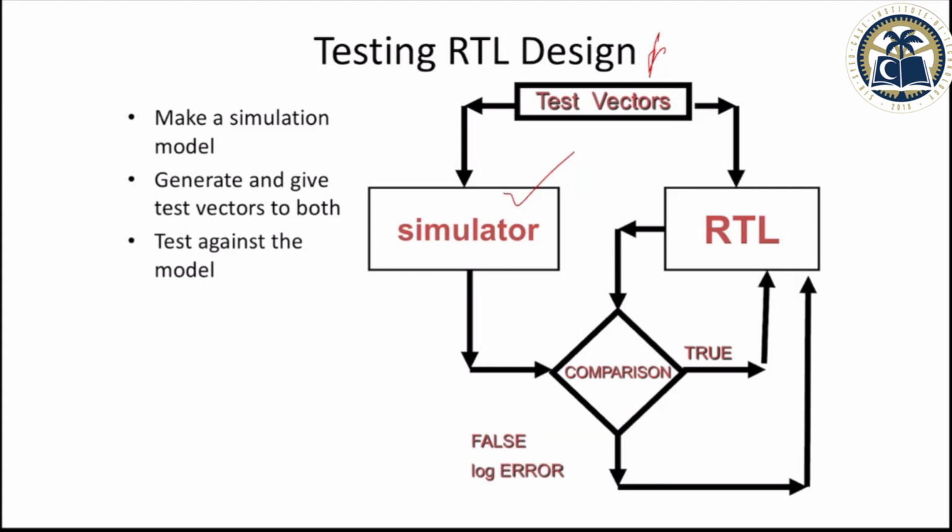So there is a lot of creativity in developing the test bench, especially in how you generate a test vector that can give you maximum coverage of your design. Coverage means that you ideally switch every transistor from 0 to 1, and in relation to one transistor, a combination with the others, like this 0 to 1, then this 1 to 0, and this also. If you start making all the combinations and permutations, it is not actually possible, even for a 32-bit adder, adding 32-bit numbers.